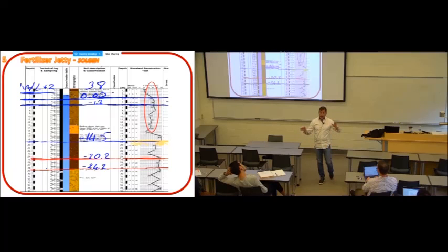Do you have any idea what the bearing capacity is if you have N? Quick rule of thumb, you divide N by 9, and that's your allowable bearing capacity for a spread footing in TSF, or kilograms per square centimeter. I use it all the time to impress people on site.